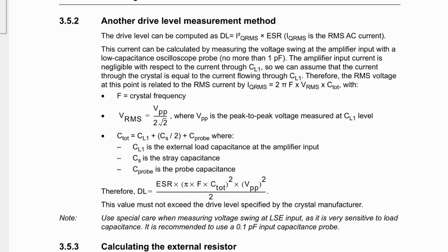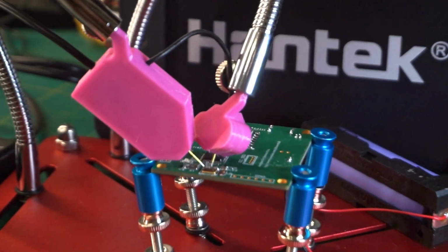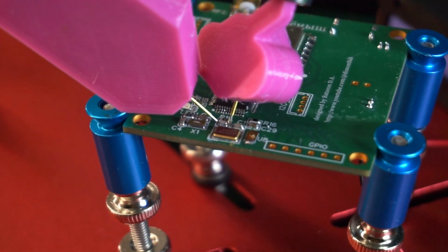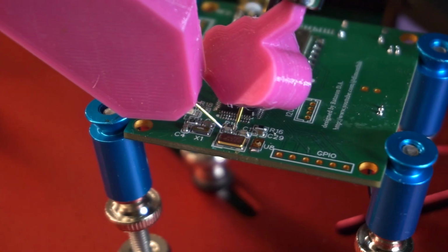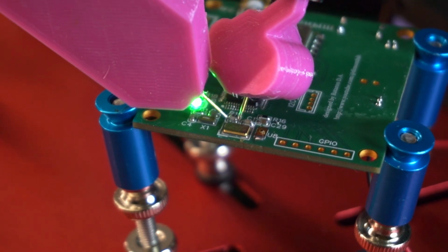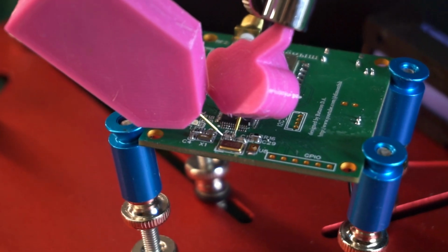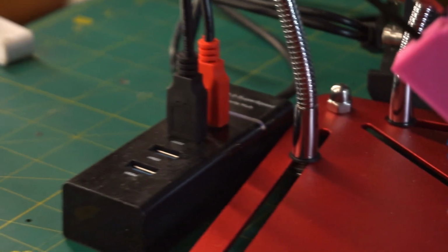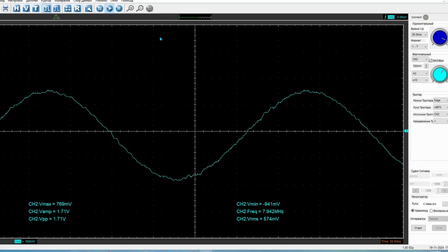The point is that including the probe into the circuit changes the value of the load capacitance. So we resoldered the capacitor and on the output with the probe connected, achieved the specified capacitance value with the required accuracy of plus minus 1 picofarad. Let's take some measurements. I connected the probes in the circuit to the capacitor C mesh now. Selected the output of the necessary information in the oscilloscope. After adjusting the settings, I finally got the desired figure.